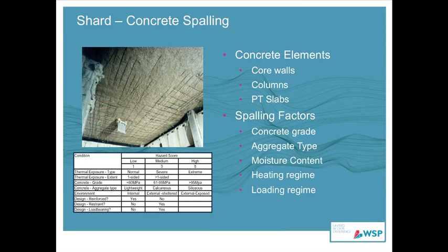I won't spend a lot of time on this. Because there were concrete areas, we were also asked by the DS to consider things like spalling. In terms of high-strength concrete, most of the high-strength concrete in the Shard is at the bottom of the building, to try and minimise the members down there. When we get to concrete at the top, the concrete becomes more normal strengths. So we used a qualitative method from the BRE to assess where we would take any remedial measures in terms of concrete mixes, etc., to reduce spalling. So that was considered for this particular structure.